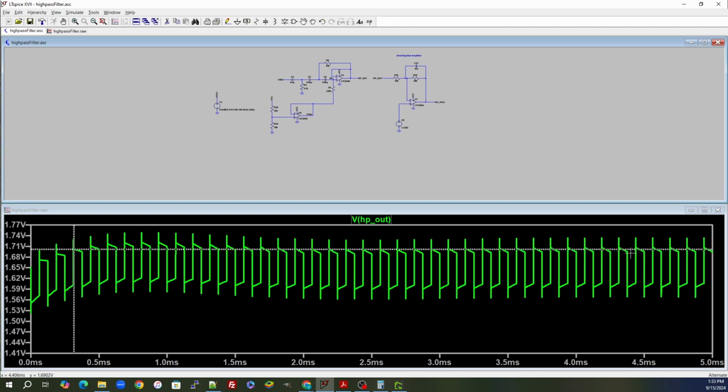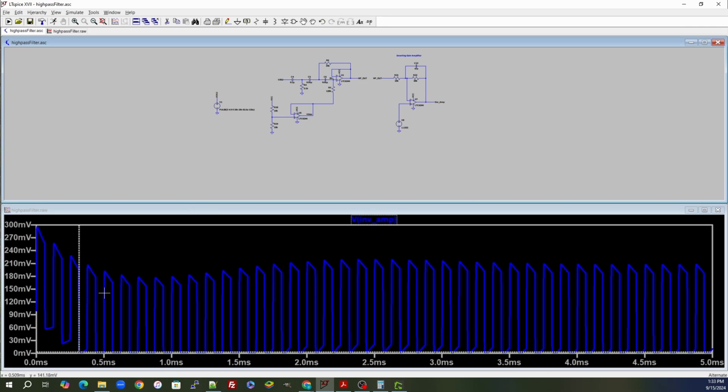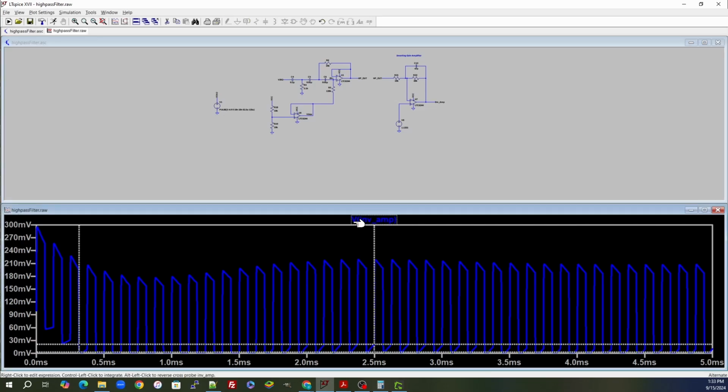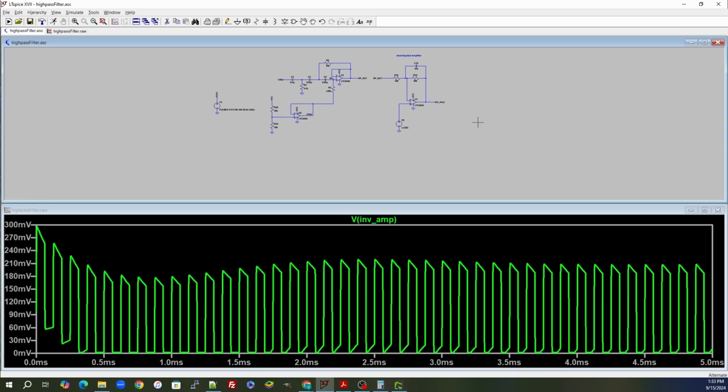you can see there's our high pass filter coming out. And if we look at the output of our thing, we got exactly what we want, right? We can see here it goes from 0 volts, and we can see the whole signal because we don't really bottom out. We can actually see it climbing up. So we got good bottom range.